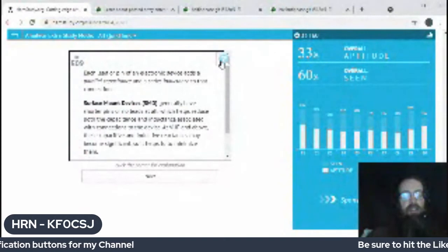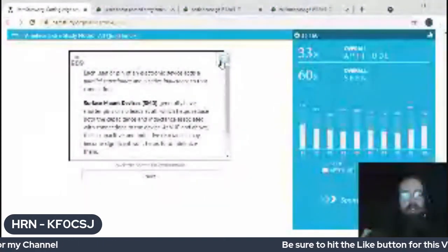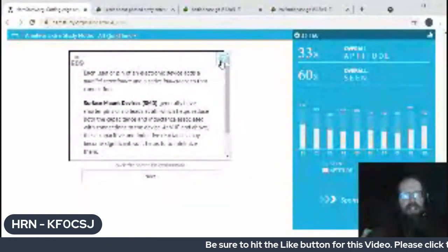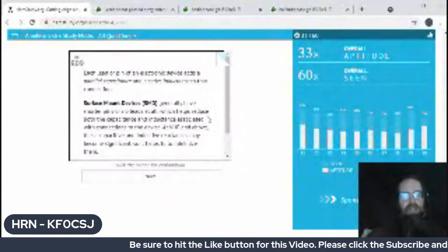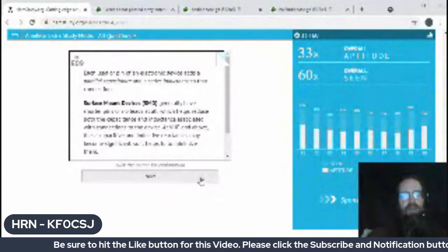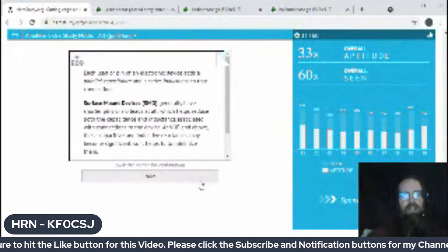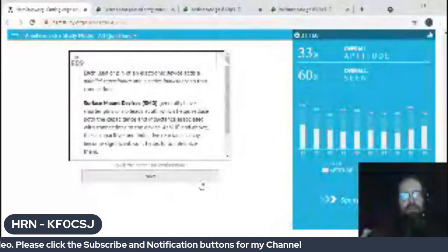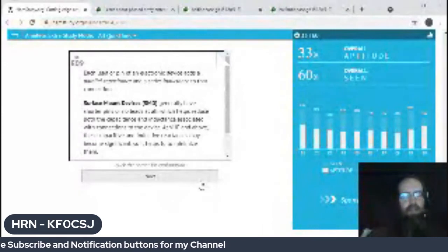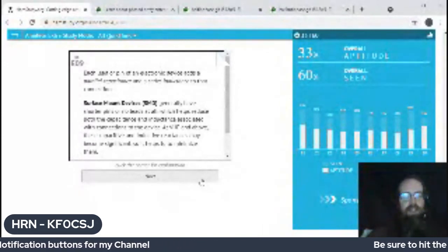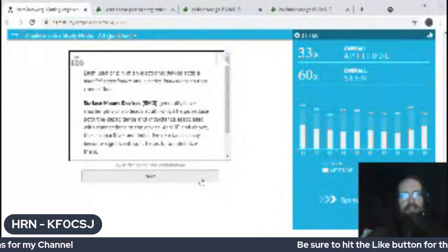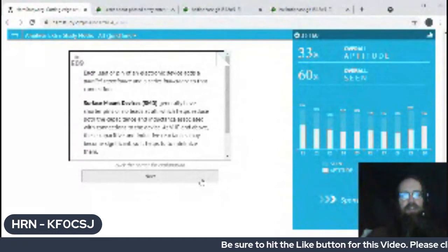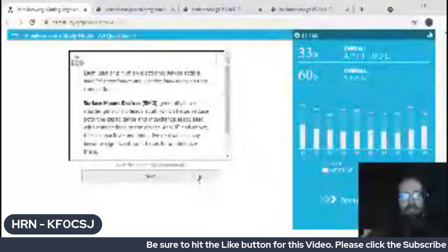There is a similar question with integrated chips, asking why integrated chips do not have legs on them in the UHF spectrum. That is because when you start getting into the microwave range, the legs can actually start becoming resonant.